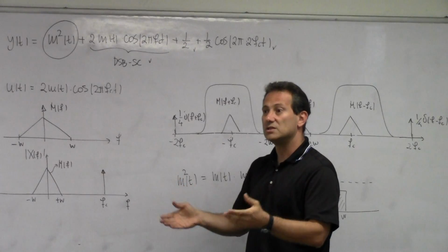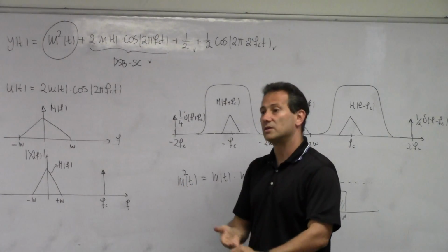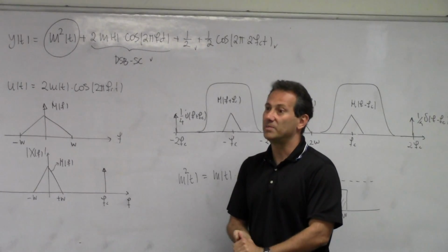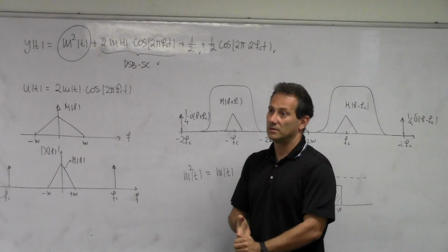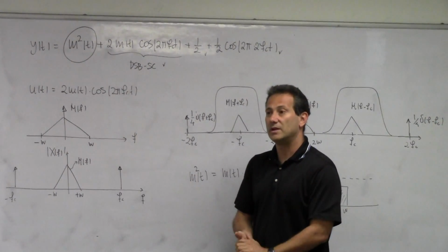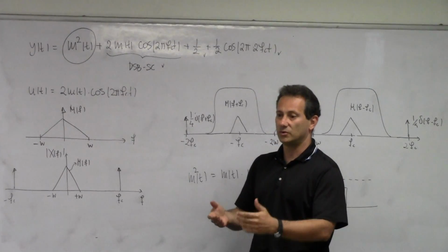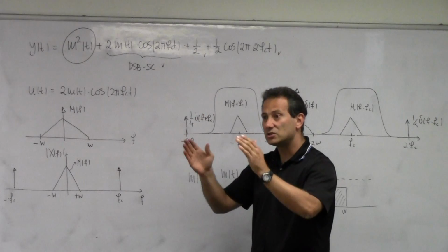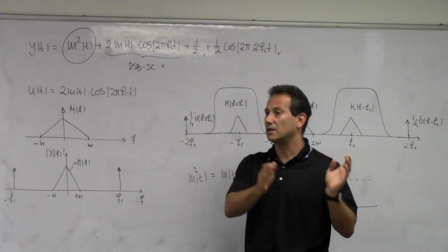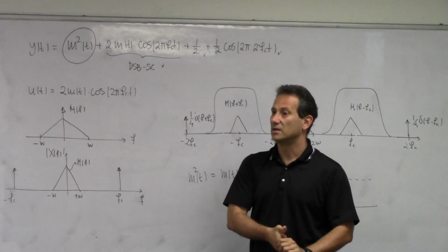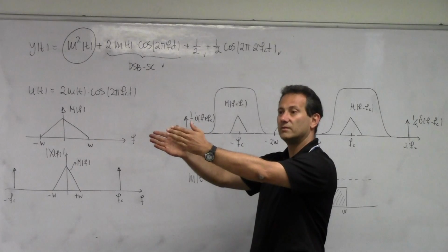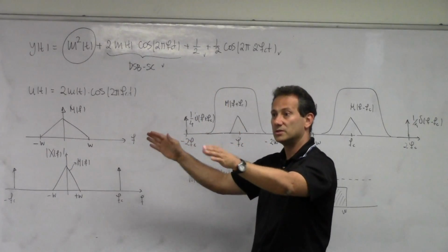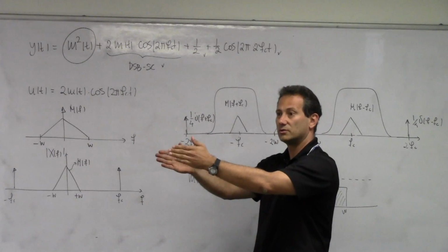So in every communication system, you're going to have both. You're actually going to have multiple filtering stages. Most of them are going to be bandpass stages. If you look at a typical radio receiver, what we call a superheterodyne receiver, it will have at least two bandpass filters and a low-pass filter on the receive side. First is the front-end filter that sits right after the antenna, rejects all the noise, and lets only your signal go through.